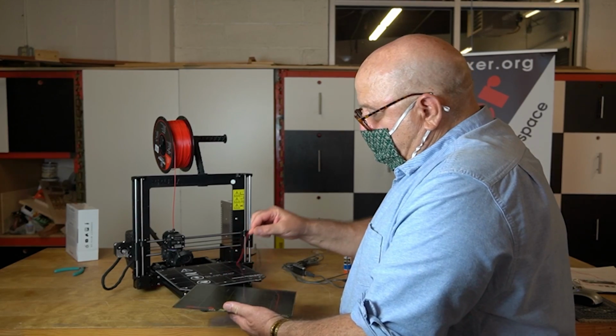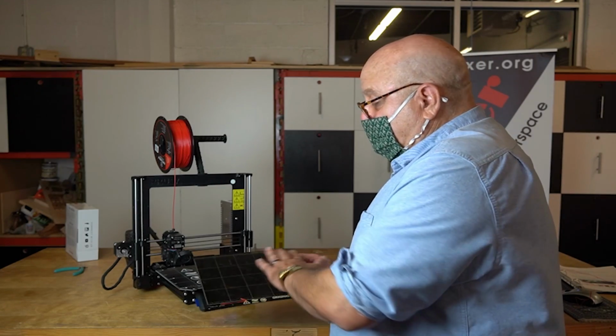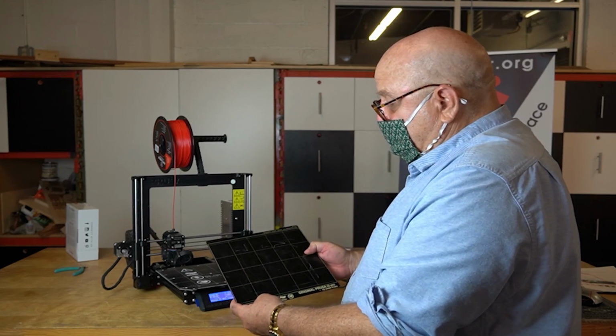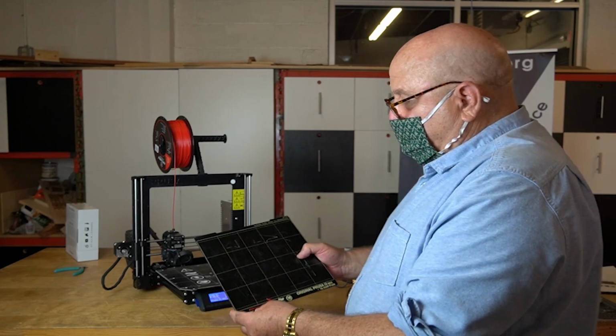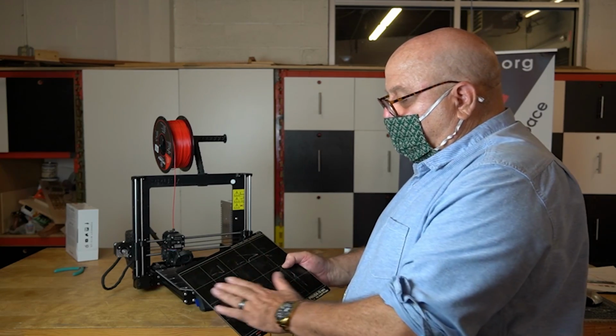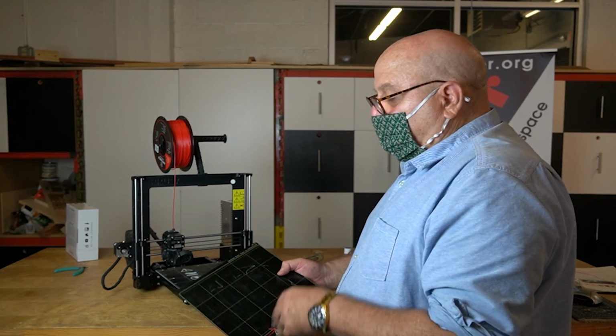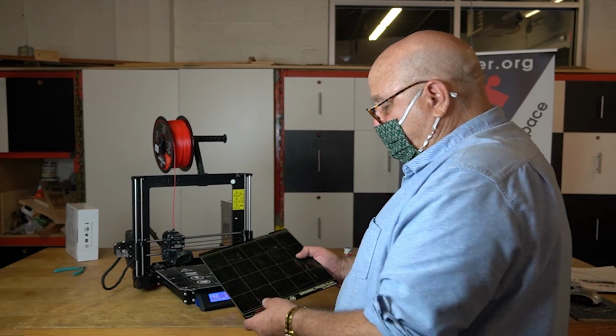Or you can pull this plastic off by your hands. Often you can't. Sometimes you'll have to use a putty knife. The other thing is that glue is water soluble. So when you finish printing, you want to take this into the bathroom, wash off the soap, so the next person who may not want to use glue will have a clean surface to work from.